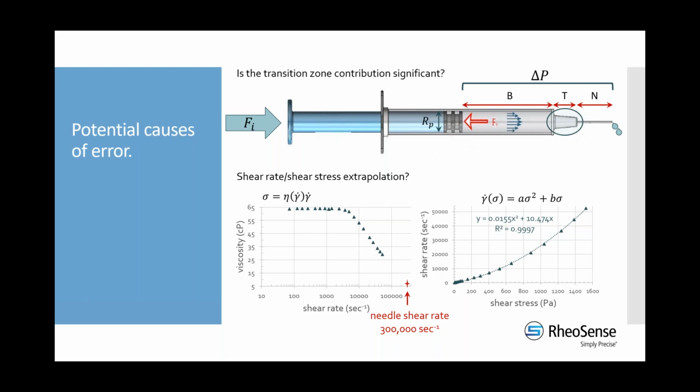So that could be something that we could look into. And there are certain formulations that we sort of maxed out on shear rate because we maxed out on flow rate, whereas others we maxed out because of pressure limitations. So on the ones that we maxed out on flow rate, we can actually start investigating this by using our new instrument, which was just released, the MVROC2, which has a broader flow rate range. So hopefully in the future, we'll start to address and see if that is one of the major factors.